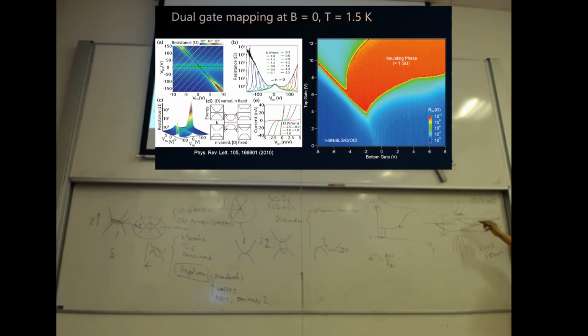That's how, especially if you measure at room temperature, you'll get a U-shaped field effect curve. So the conductivity has a minimum like this. Only when you cool down the system will you have a partial filling gap showing up at the end. So at room temperature, you will have only a U-shaped field effect transistor, which is not insulating. It's just not insulating yet. You have to cool down to low temperature, and that gap doesn't give you the large resistance.